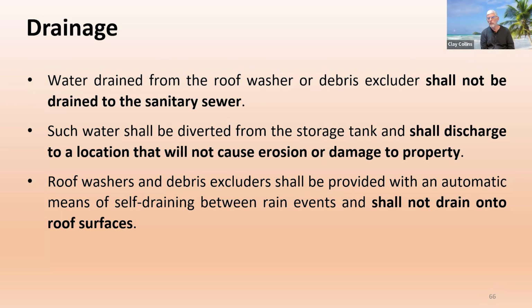And while it should run to the side, a lot of times with enough volume from a steep enough roof, it just runs right over it. But recommending the gutter to protect it is my approach. But you certainly should note to the client that that water runoff over time can be an issue.